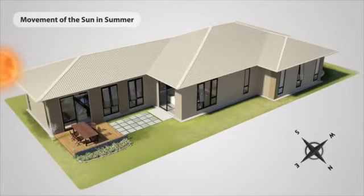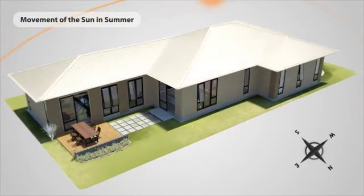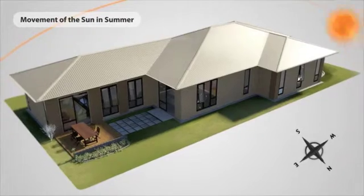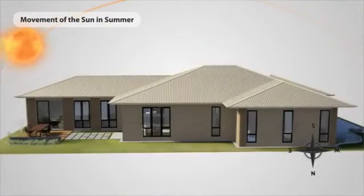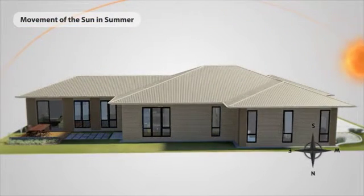It's important you understand the movement of the sun in relation to your block selection and your home design. You can see here the rotation of the summer sun. In summer, the sun is higher in the sky. By designing your home correctly, you can make sure the home is shaded in summer with eaves and other shading devices. From this view, you can see that the sun is not streaming into the north side windows, keeping the home cool on summer days.